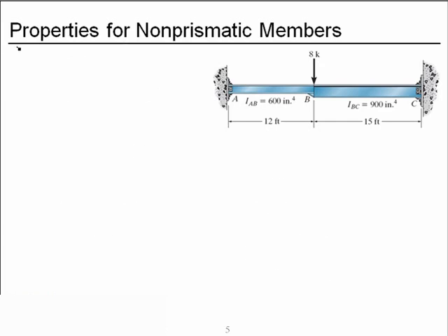Now step 4. Creating the conjugate beam. To do that, however, I need to convert our moment diagrams from the previous slide to M over EI for the beam.